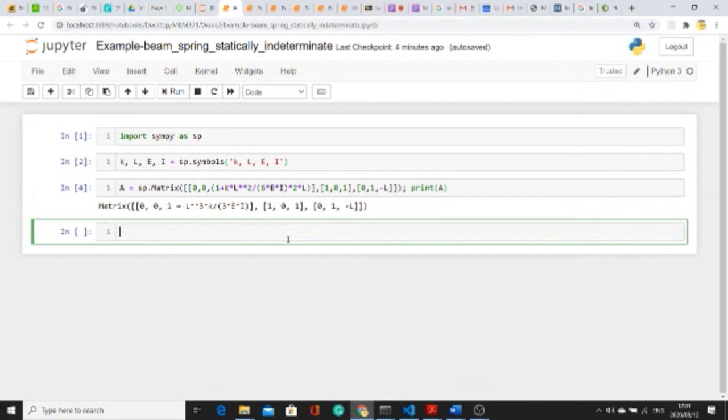Just want to make sure that you're with me on why it's so important that once you've got an answer, that's when the problem really starts, is to say to yourself, do I trust the solution? And again, we can do the sanity checks. What happens if you make K very, very low stiffness, or essentially near zero stiffness? Do I recover the solution of a beam with only a Q loading with no spring there? Or if I make K very stiff, do I recover the solution of a roller on that edge where the spring is? And that's the kind of stuff I want you to be able to do and play with in these tutorials so that you can get comfortable with it.